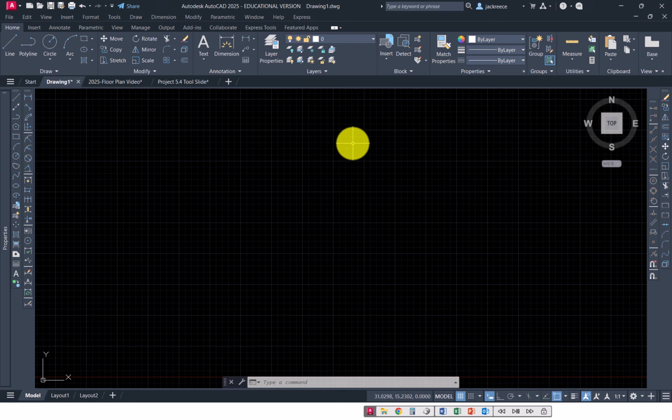In some of these early exercises, the book will tell you to draw on layer 0, and that's fine when you're just learning how to do things. Once we start creating layers, you don't want to draw on layer 0.